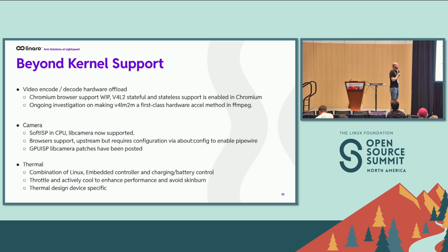And the last one, which is quite important on these kind of devices, is the whole thermal setup we're having. So thermal, while we can read temperature values in the kernel, we can set up thermal zones to throttle maybe the CPU, maybe throttle the GPU and stuff like that. You can have all of that, but there's a lot more in such a system, how they interact, how to actually make sure that you synchronize how the efforts are done.